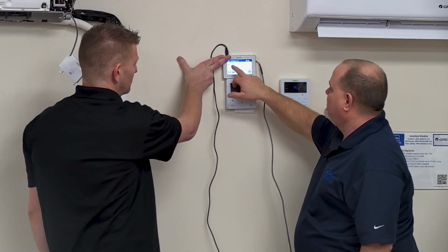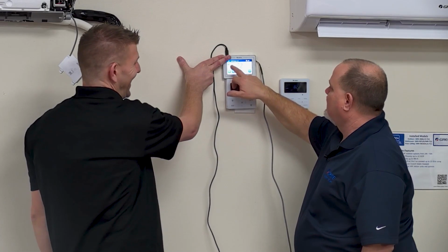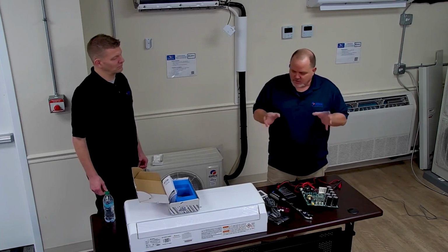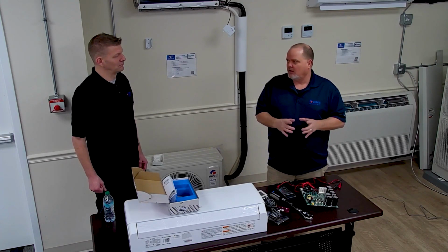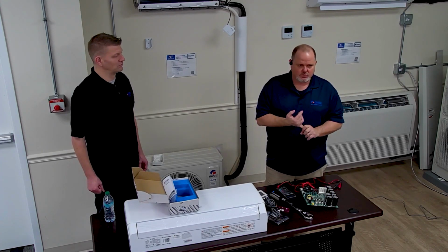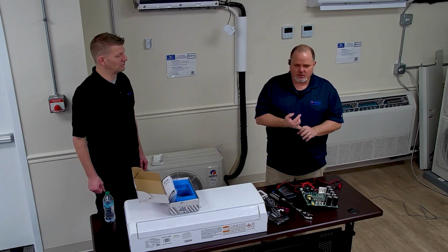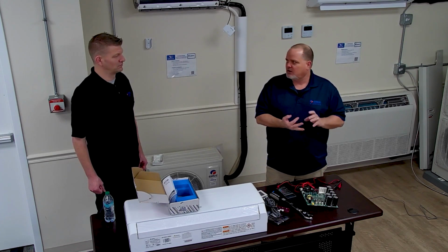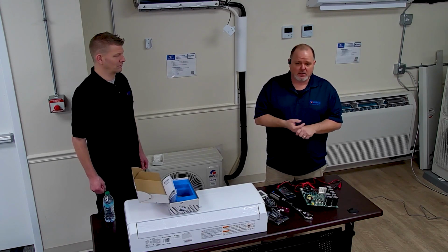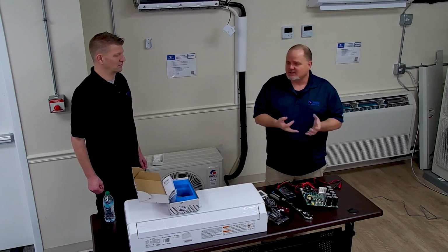So what we're going to do, and give JD a break from holding this thing up here, we're going to shut it down. All I'm trying to tell you guys is the service tool gives you what you need to know to figure out what's going on with that machine. You don't have to hook gauges up to it. You don't have to do a whole bunch of thermistor readings and stuff like that. You can go to the indoor unit status and look at the indoor ambient, and if it says it's 68 degrees, is it 68 degrees? If it's not 68 degrees, if it's 85 degrees in there, then we need to dig into that indoor ambient thermistor, right? Right. Oh yeah.